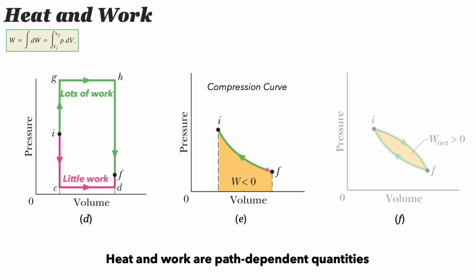Now let us see this one. This is different. This is a thermodynamic cycle, which means first we go from initial state to final state and from final state to initial state, right. So we follow this path in going from initial state to final state and back from final to initial. This makes a loop, right. So the work done will be equal to the difference of the work done between these two processes. First we go from initial to final state, the work done will be the total area under this curve, all the highlighted one from here, all from the horizontal axis.